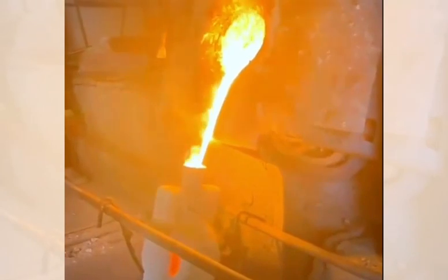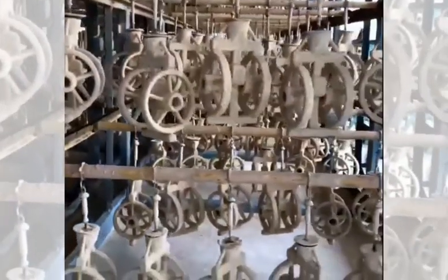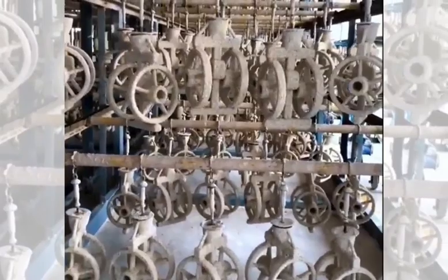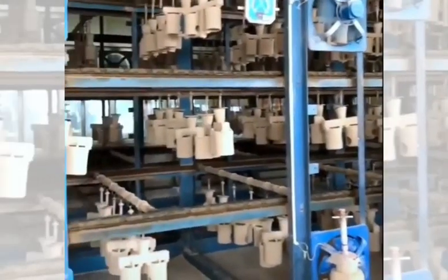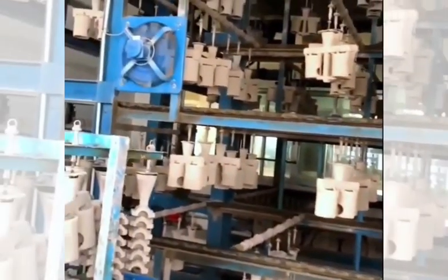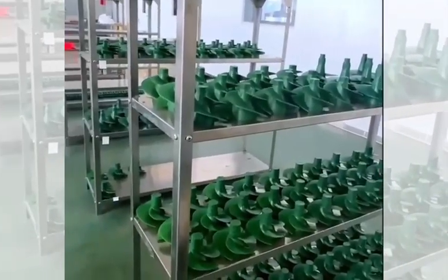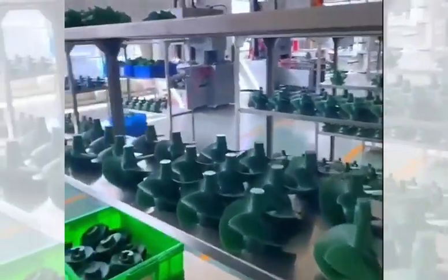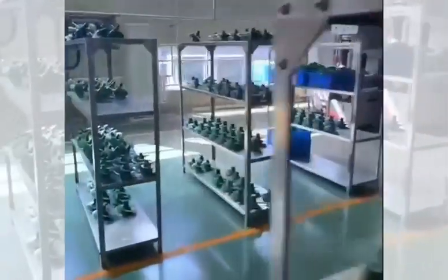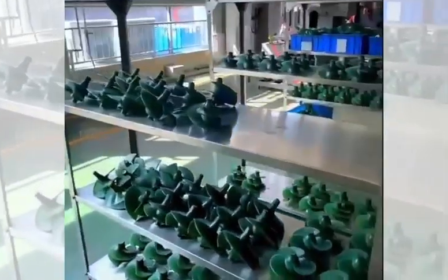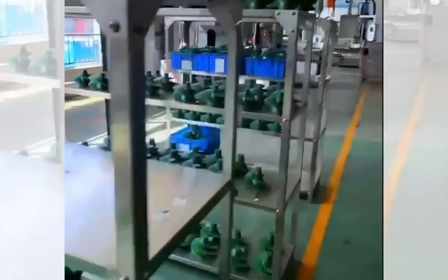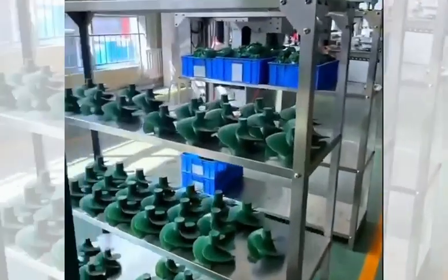Cost. Investment casting is a labor-intensive process that results in superior dimensions and a good surface finish, making it a relatively high-cost casting method. However, it can potentially reduce or eliminate the need for secondary machining, saving both time and money. Die casting, on the other hand, incurs higher tooling costs and sometimes requires post-machining operations for finished components, making it more cost-effective for large order quantities.